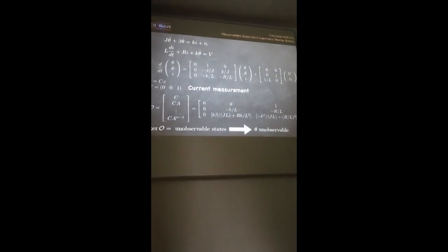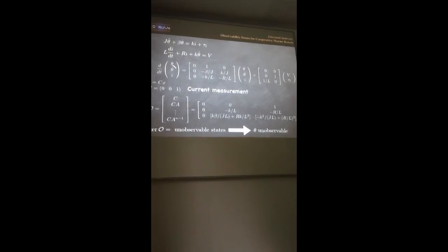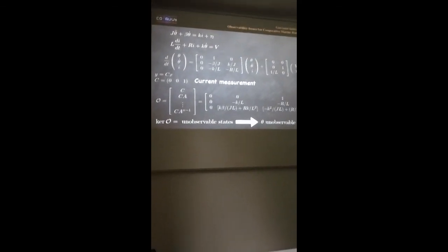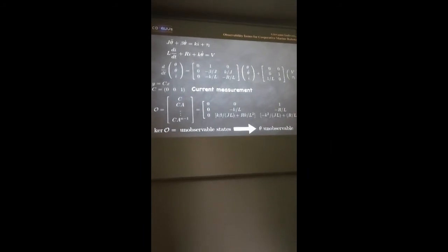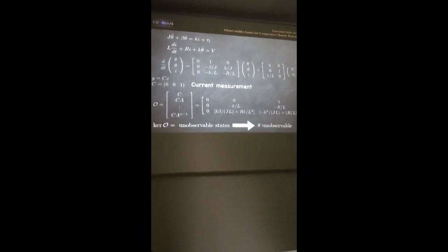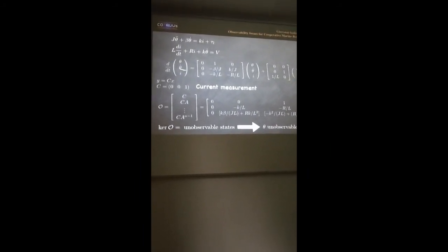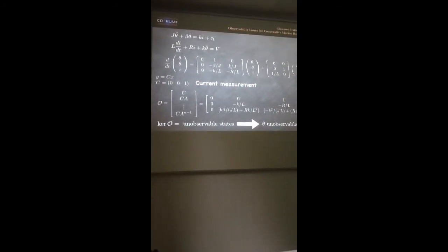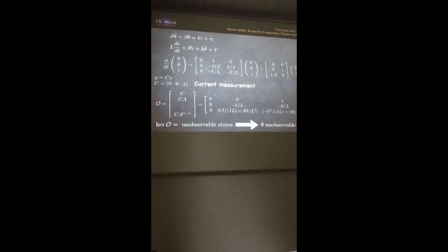So the best in marine applications, although it's not very common because especially cheaper motors don't allow you to do that, would be to measure both the angular velocity and the current. You really don't care about the position. You don't care if the propeller is turned 30 degrees or 50 degrees. You don't really care about that. But the other two variables are necessary, or are likely to be necessary.